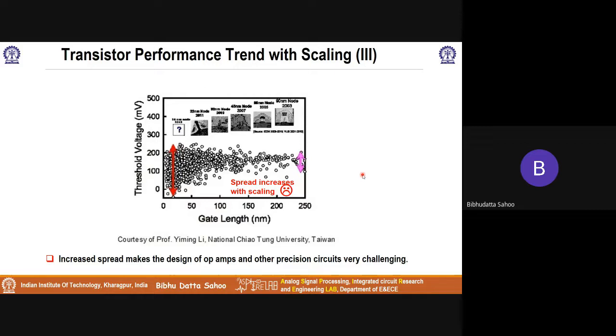But there we are not using all transistors with 7 nanometer channel length. We are mixing transistors. There are 3-4 flavors of transistors: thick oxide, thin oxide, and midway between. We use all the variations, and make only the speed critical devices minimum channel length. Others we make larger. Okay, sir.